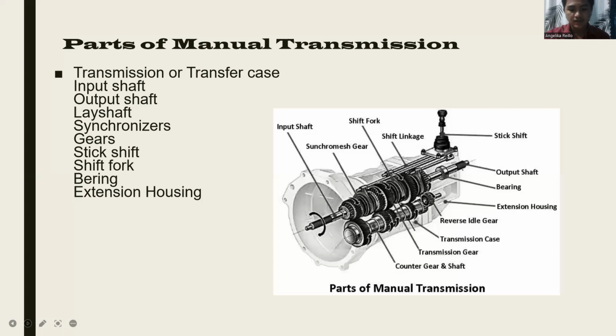Synchronizer. The synchronizer facilitates engagement between the collar and gear to synchronize their motion. Plus, it helps to adjust the shaft speed so that gears align faster as you shift. Sometimes the speeds can vary, so the synchronizer helps to avoid that.